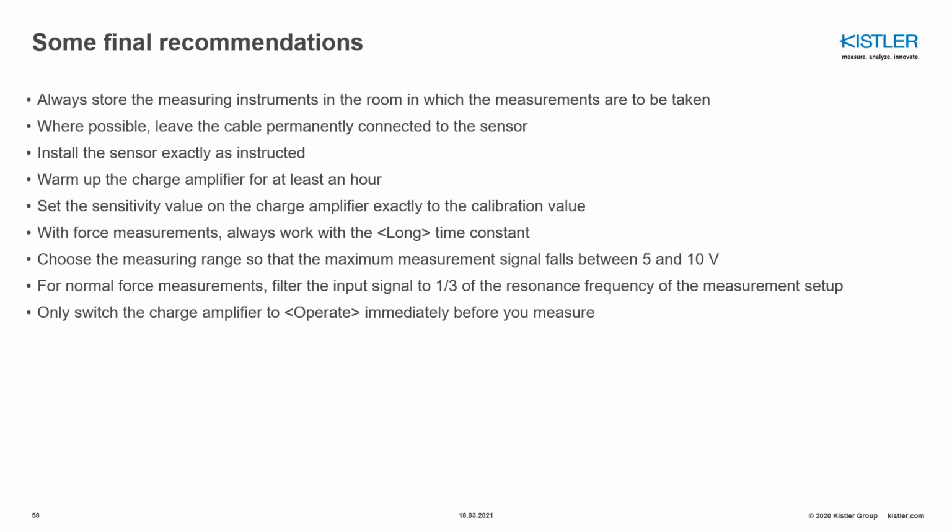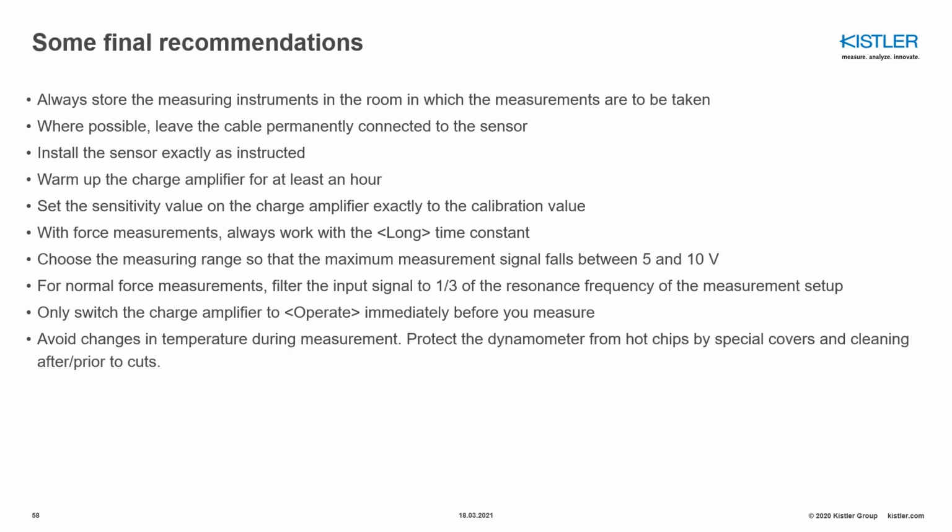Only switch the charge amplifier to operate immediately before you measure, or you can also start, of course, your measurement with the software. The reason to start just before you are cutting is that if you start the measurement while the machine is moving and making accelerations, coolant pumps, rotations, and so on, then you will have some sort of disturbances in your measurement. Avoid changes in temperature during measurement.